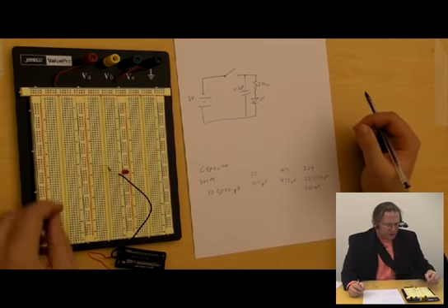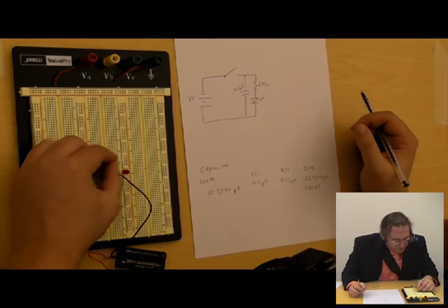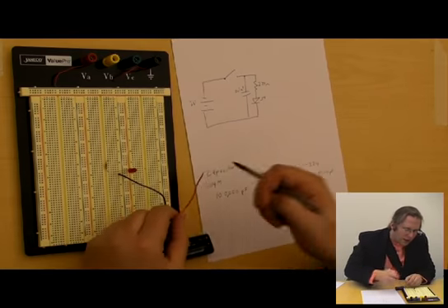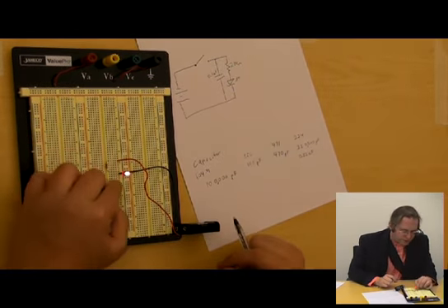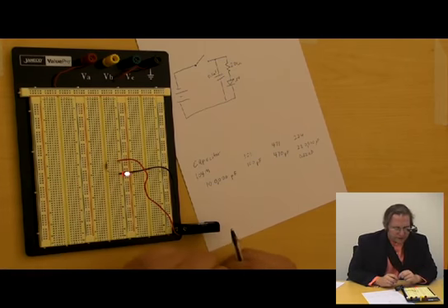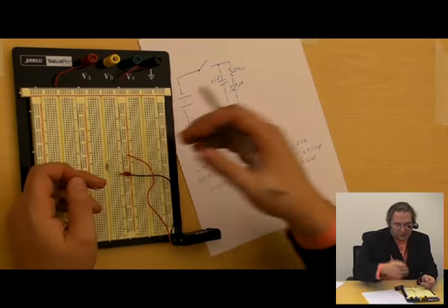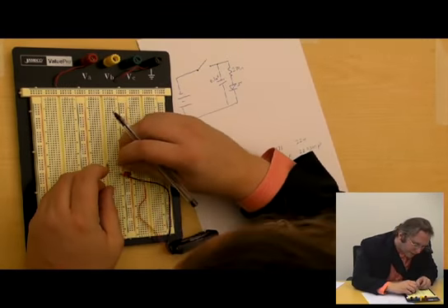Well, let me actually make the circuit a little bit simpler for me to play with now. So I have power going here through the resistor and through the LED. Now I want to put this capacitor across the battery, basically in parallel to the LED. So I'm going to undo my circuit so I don't accidentally power something I don't want to and fry the circuit.